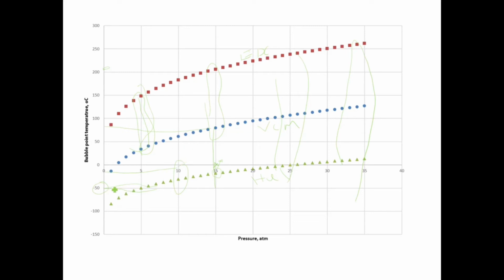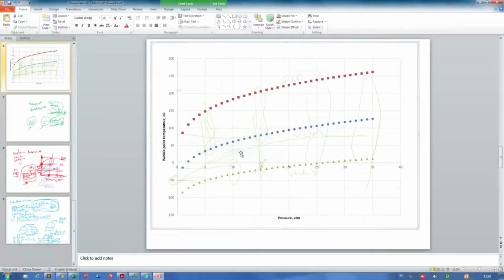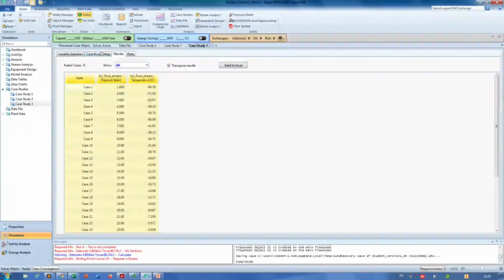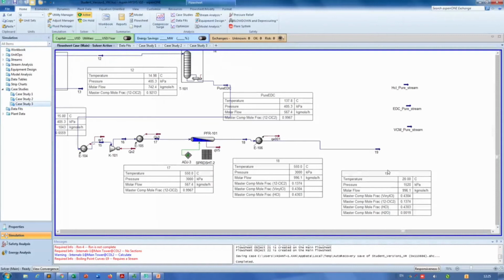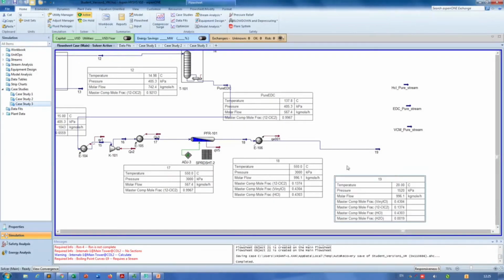Say, if you have a mixture of vinyl chloride monomer and maybe all three, then this curve may differ. Okay, so let's close this. So we learned how to get the fluid properties using Aspen HYSYS, and we also provided some justification for using a distillation column to get the pure vinyl chloride monomer. Okay, I think we've done the job, so I'm happy with what I explained so far.